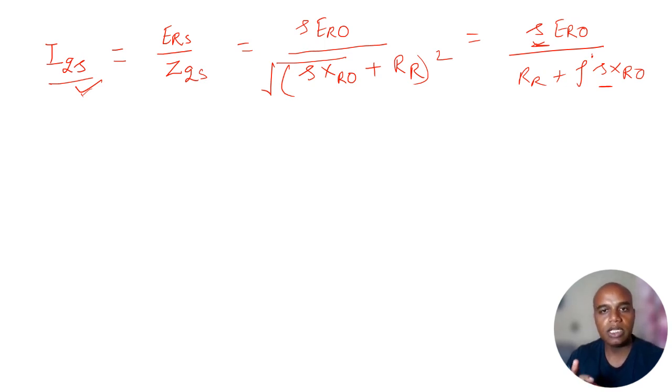But for the simple calculation and approximation, if I want to bring that flavor into my equivalent circuit diagram, I have to show that the rotor is a fictitious stationary part. Let's assume it is not rotating, or bring it down to something like a stationary secondary circuit of my transformer. So how to do that?